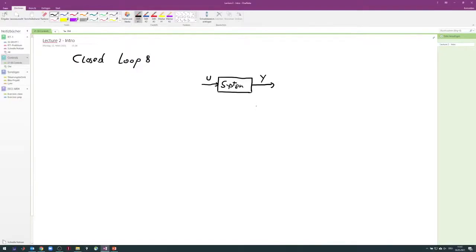Aircraft cannot. This is the bad news for aircraft engineers, because you know from yesterday that you have a coupling in the lateral axis. What I tried to convey yesterday is that when you try to fly a turn, you need the ailerons and the rudder to make a nice turn, right? So this does not hold. However, for controls, we're going to stick with that. Okay, so if we want to do automatic control, we have something in mind which we call reference, right?